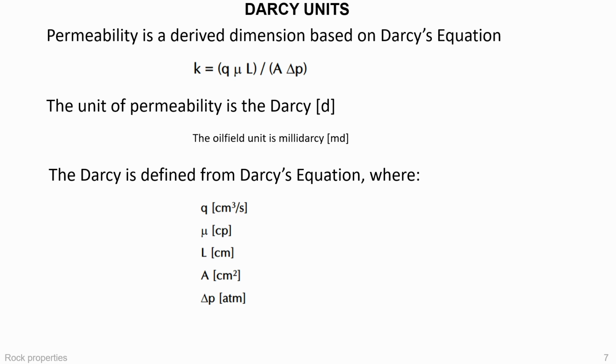Here explain what 1 Darcy physically represents. The Darcy is defined from a reference flow condition in Darcy's law using standard parameters. If permeability is higher, the same pressure difference produces higher flow rate. If viscosity is higher, the same permeability produces lower flow rate. This is why heavy oils produce more slowly even in good rocks.